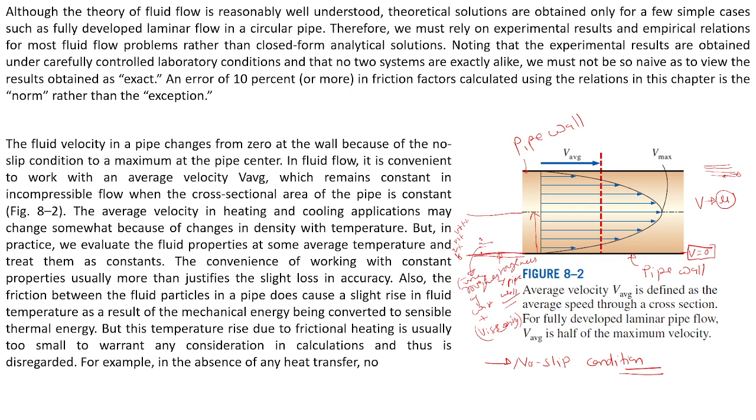So similarly, going up to the center of the pipe, your velocity is maximum at the center of the pipe, and the effect of roughness is very less, negligible or minimum at the center of the pipe.